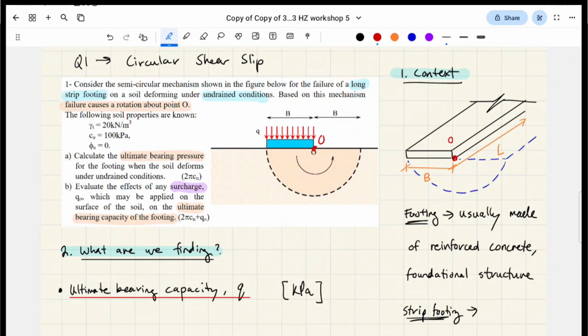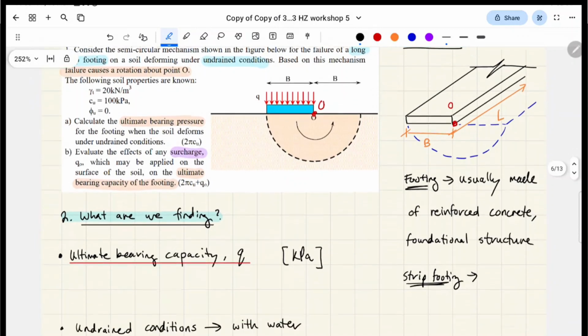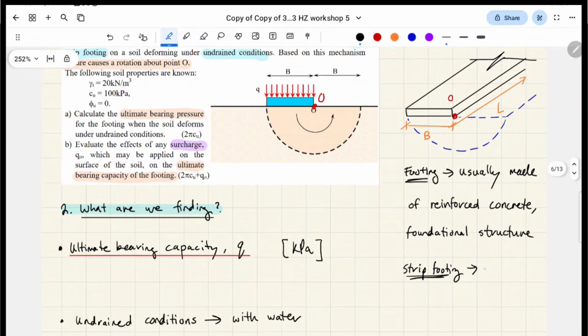If you go on to do advanced concrete, in that course, we look at this whole setup again and analyze the ultimate capacity of the concrete itself. But in this course, we actually care about the bearing pressure of the soil, which I'll talk about in a second. Let me just write that in strip footing cases, we have that B is much smaller than L. So L just goes into the page for however long. But we're going to do all our calculations in terms of this per 1 meter run. Got it?